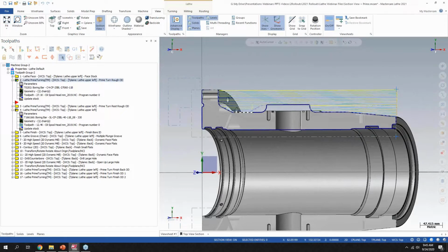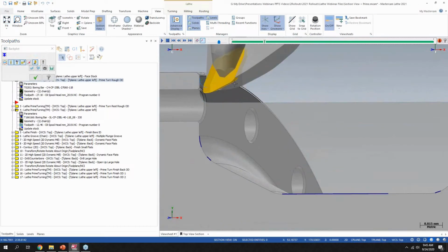And the best way to do that is to talk with your Sandvik rep, and they can recommend either setup applications or tool applications, depending on what materials you're working with, what tools from that library are viable for this. And if you don't have a sub spindle, a tailstock can help a lot because you don't want that material pulling out of the chuck.